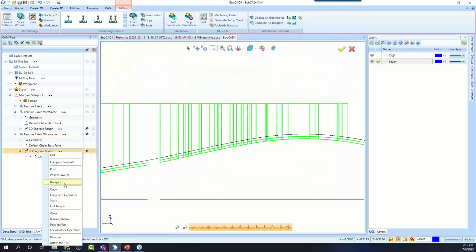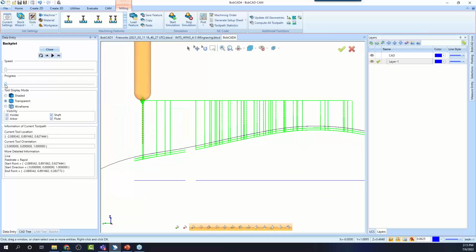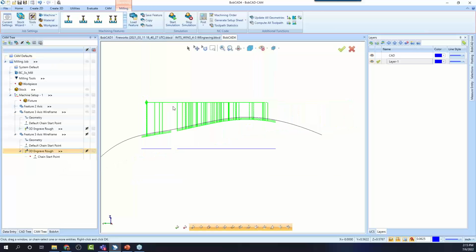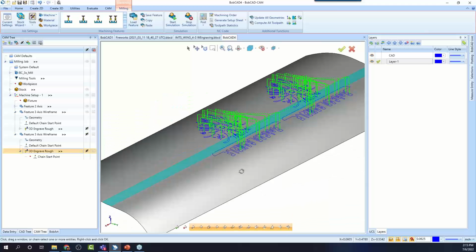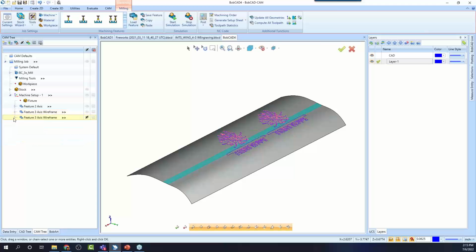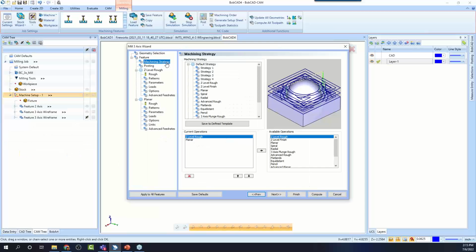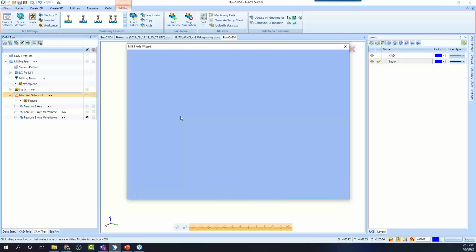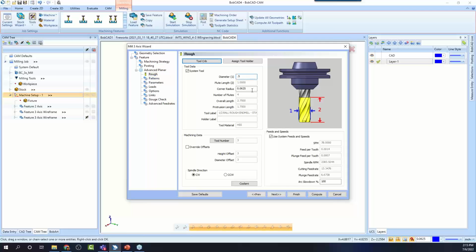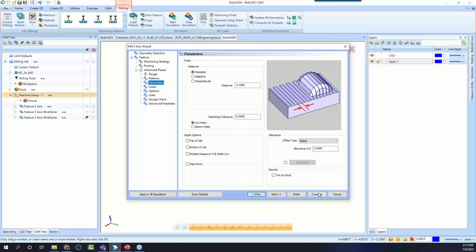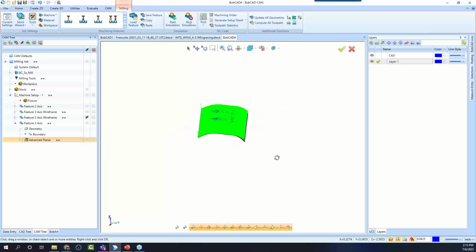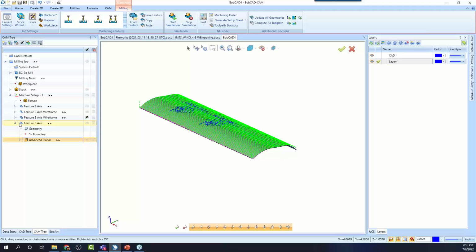tool size down a little bit, so you can kind of see the difference there. We don't really have, like this one, we would have had to already machine it. So what I'll do real quick is load a 3-axis routine for the model here. I'm going to do just the planar. With something like this. All right, so that way we get some toolpath to finish that, right?